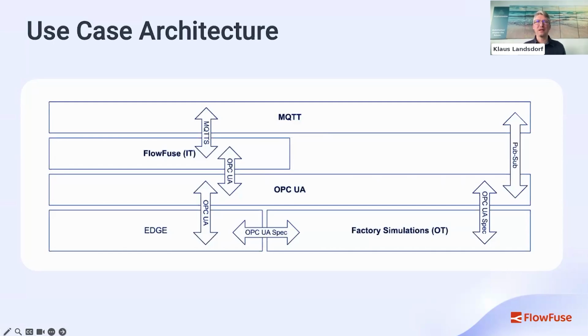Because sometimes it's really a problem in real-world projects that you get an OPC UA server and you have something like ABCD, whatever, from 20 or 30 years ago in a PLC, and that's something nobody can work with. It is not really an information model at the end, because it should be readable for humans and machines when you have a really nice information model.